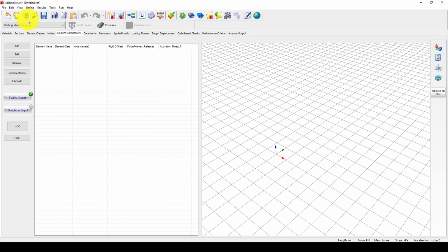So in this step time, most of the beam columns are yielding. But in case the performance ratio is quite high, then there will probably be some crushing or some fracture. We couldn't find that fracture because the time step is quite large, and it's a little difficult to find it. But most beam columns have reached yield.